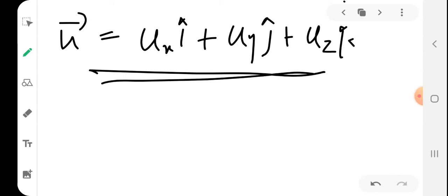So we assume the displacement is defined throughout the volume of the body. The displacement vector u of any point P belonging to that body is known once its coordinates are known. If the initial coordinates are known, you should be able to determine the displacement vector. Then we can say that a displacement vector field has been defined throughout the volume of the body.